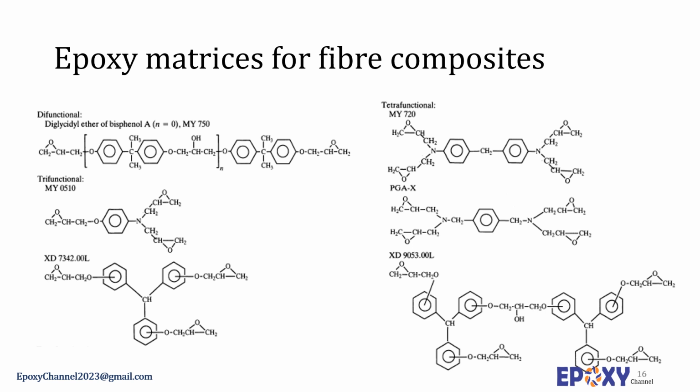cured resins. Other thermosets, for example phenolics or polyimides, produce volatile organic compounds since these involve condensation rather than step growth or addition polymerization. Therefore, in those systems, because of volatile formation, high pressures and more complicated cure schedules are required to prevent damage accumulation. Epoxies generally satisfy the above criteria, and they also offer a low shrinkage.